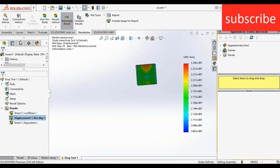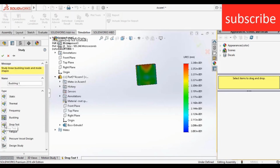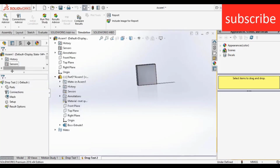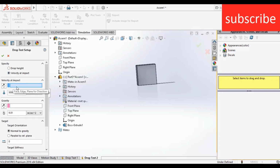Now let's talk about another thing, new study, but this time I'm going to use velocity at impact. So here it is asking for the direction in which the velocity is going to be. So select this edge because it is acting downwards. As you can see the arrow is pointing upwards, so click on reverse direction.